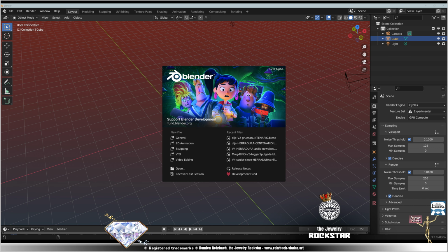Okay, so from here, I'm not going to make the clipping just yet. Before that, I'm going to add the solidify modifier with an offset of 1 to the outside and a thickness of 1.5. And this is starting to get better and better. Okay, so the important element here is that the body of the ring holds the bezel. And anyway, we are going to hide the gemstone bevel.